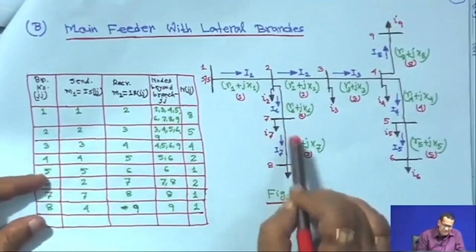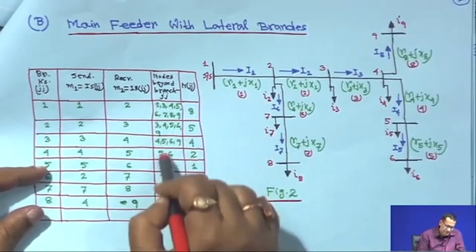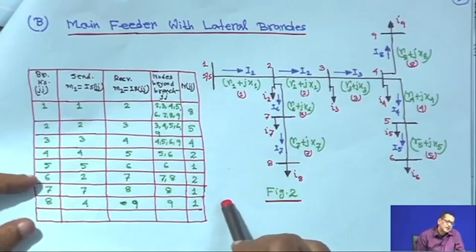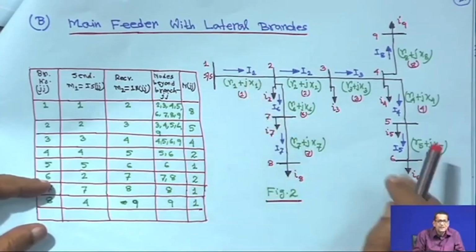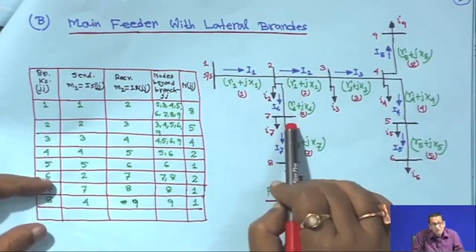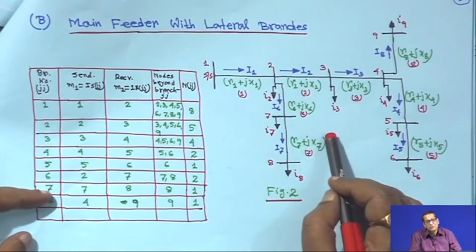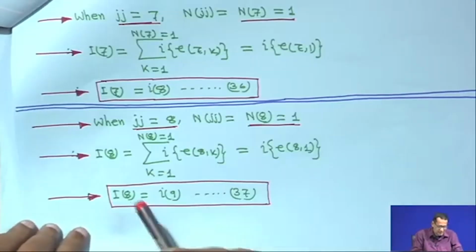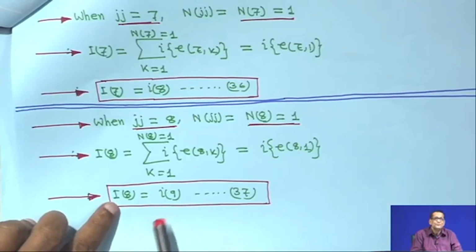That means all these E matrices that I asked you to put in an array, even if the diagram is very large, you can make this matrix easily and feed it into the computer to read this data. Then no identification algorithm is required; automatically it will read it and find the branch currents, if of course the load currents I1, I2, I3, I4 are known. How to compute will come. So, this is how I have shown you to evaluate all these branch currents.